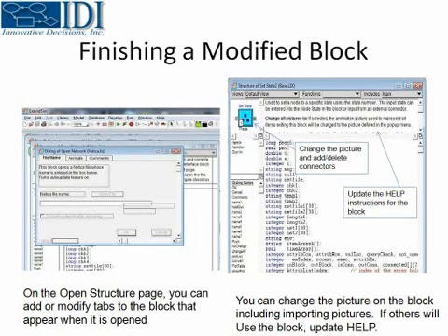So the easy way to get around that is if you don't want it visible, just use the hide function for the particular text box or whatever you want to hide, and then just move it up maybe to the upper right-hand corner or someplace out of the way. But that'll save you a lot of troubleshooting and having to go in and try to find out what code you might have to delete that goes along with that particular block.